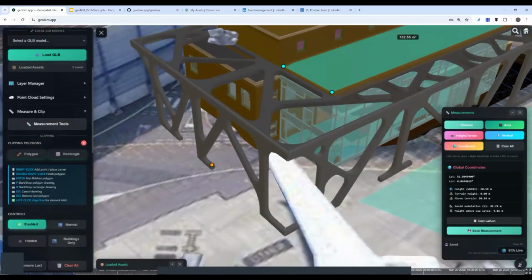But what I can show you is that 45 plus 4.81 is those 50.59. So the application will measure the difference, the so-called geoid undulation. That's the difference between the geoid and the ellipsoid, and that's 45 meters at this point on the Earth. So it's always different. I'll show you later again. Very important.